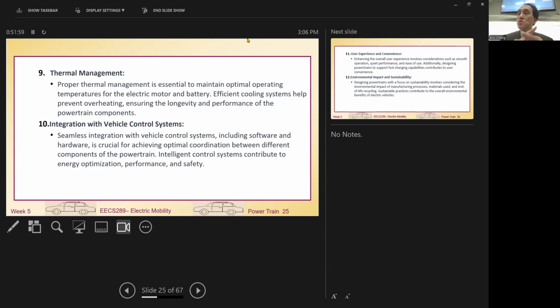All the components we see in a vehicle today have a best operating temperature around room temperature, say 25 degrees C. That includes the battery and also the motor, including PV. A PV panel, if you're under the sunshine, the temperature can go up to 60 degrees C. The efficiency is really poor. So we need to cool down the PV to 25, 20 degrees. Then the efficiency of PV gets better, close to 24%. If you heat up to 60 under direct sunlight, the efficiency may drop to 15 percent. Not worth doing that.